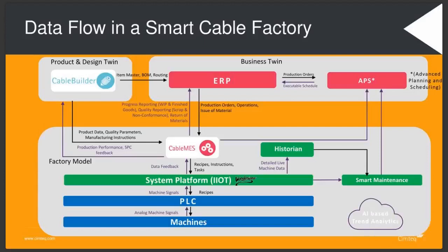Nowadays, there's artificial intelligence-based trend analytics. So you're collecting all this data, and you get data blind because you see so many pieces, so many tags of data that you can't track them anymore. There are tools out there now that monitor the history of a trend, and they will recognize automatically when something is not right anymore.